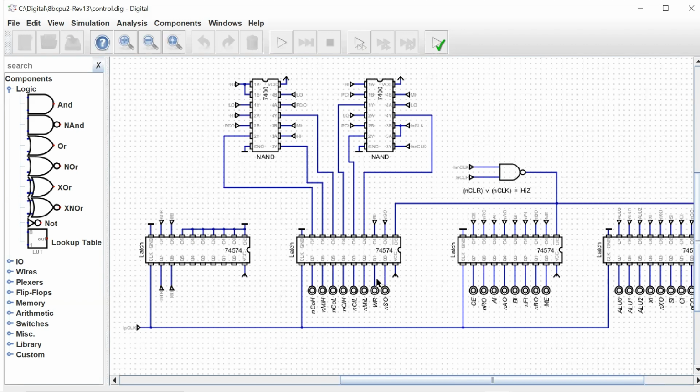This was the signal that was used to clock in the data being written to those devices. And I had to change this. What I was doing here was taking that clock signal and ANDing it with the P clock, and that was what was being output here. The write signal has to occur in the P clock phase.